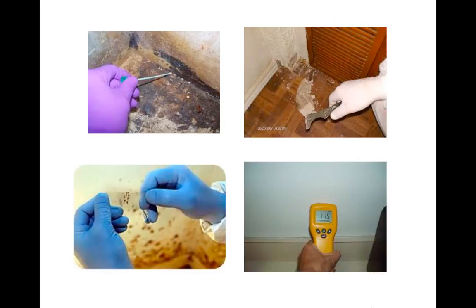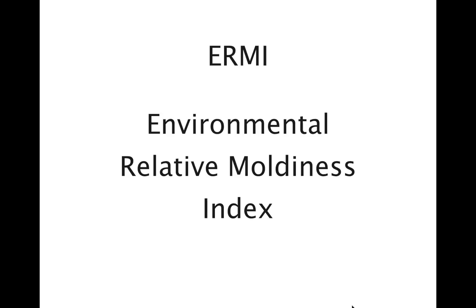That's right. Mold grows in areas where there's moisture. That's where we're likely to find mold. Very frequently, when I tell people to do a mold investigation, what I'm telling them to do is a moisture investigation. Go look where there's moisture. Go look for mold where you see moisture.